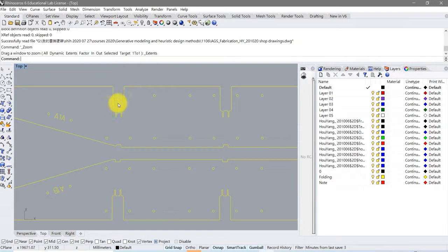What is the reason for the holes in here? Okay, because they have 2 parallel lamina going, twisting and bending. So they need some other object to maintain the distance between these 2 parallel laminas. And these holes are for some metal pieces to hold it.